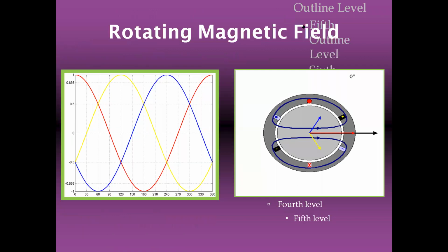See, the RYB positions are changing with respect to time. This graph shows the three-phase magnetic flux produced in the air gap. Their values and directions change continuously. Please observe the RYB color code, and this black one shows the resultant on the motor side.